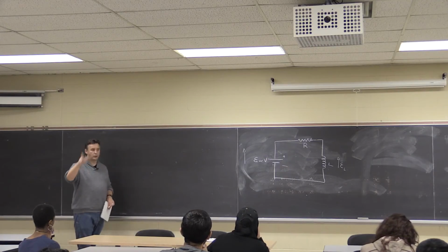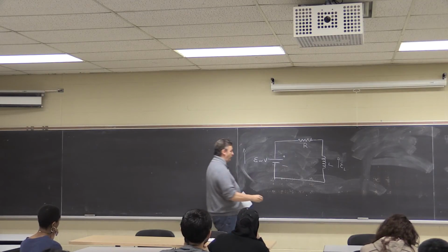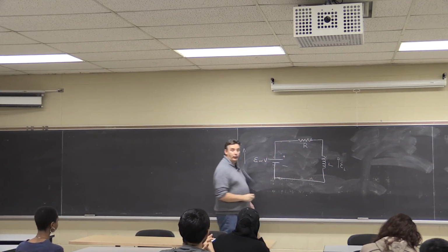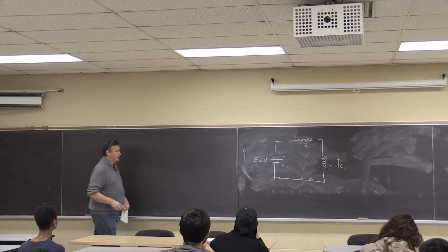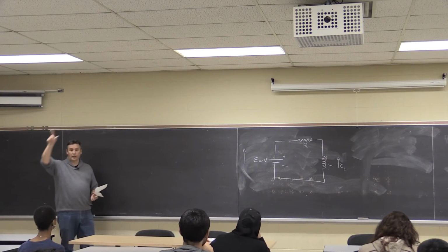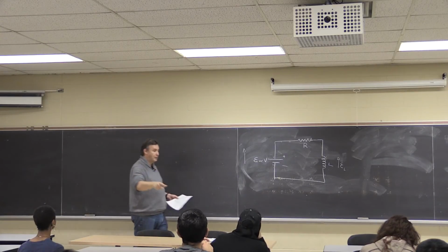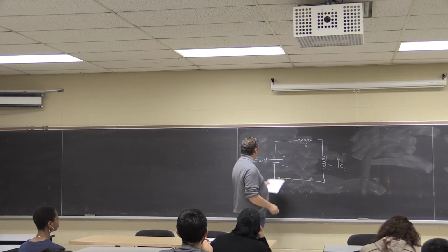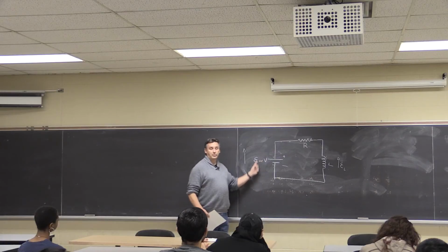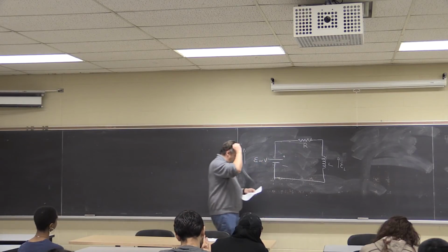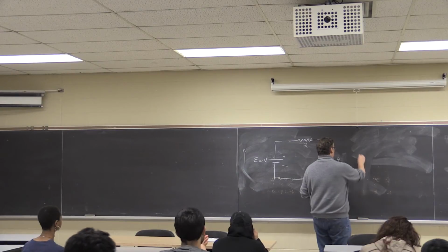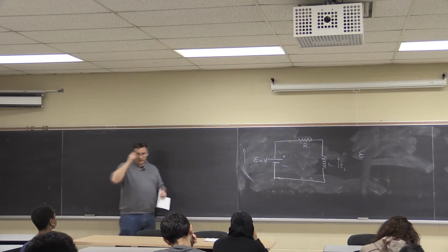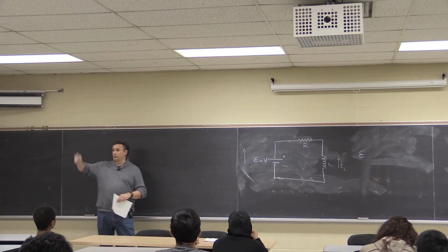His other law is the voltage law, that basically says if I start at any point on the circuit and I walk around the circuit, I get back to the same point, I'm at the same voltage. So that makes sense. So Kirchhoff's voltage law says the voltage increases and the voltage decreases around a loop have to add up to zero. Okay, so using that I can say, well, the only thing that's generating me voltage at the moment is this thing. So the voltage supplied by the battery must equal the voltage drop across the resistor and any voltage change across the inductor.